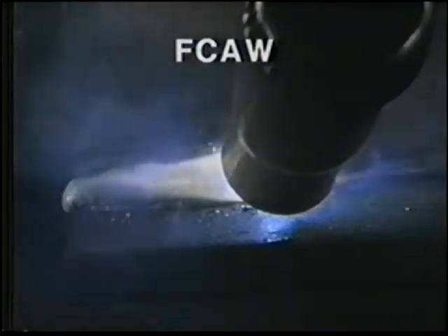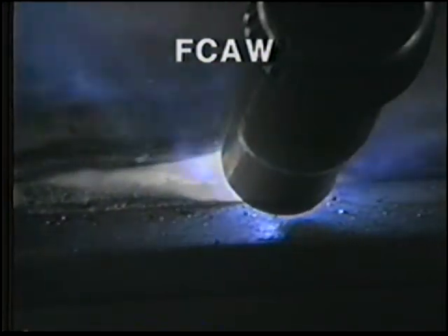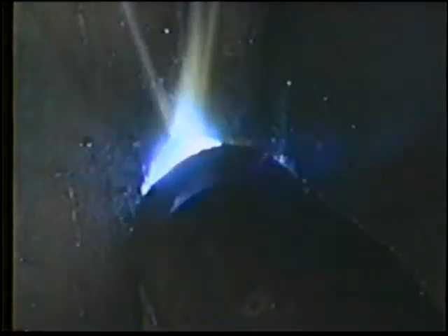On metal thicknesses greater than 3/16 of an inch, a more efficient welding process is through the use of a tubular wire called flux cored arc welding. However, on properly prepared plate and pipe, metal thicknesses of a 1/2 inch and thicker can be successfully welded with short-circuit transfer.